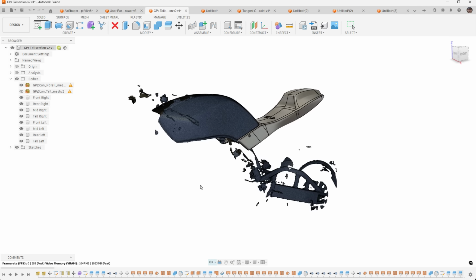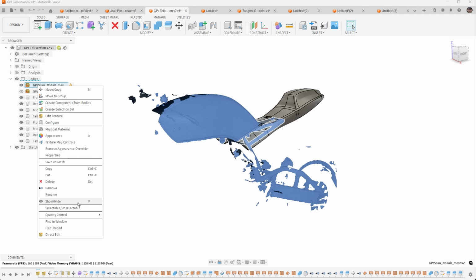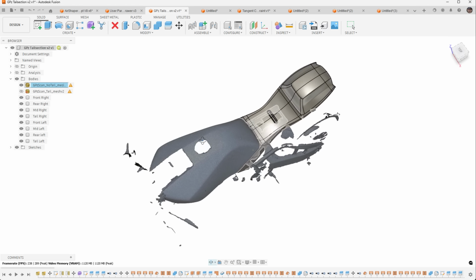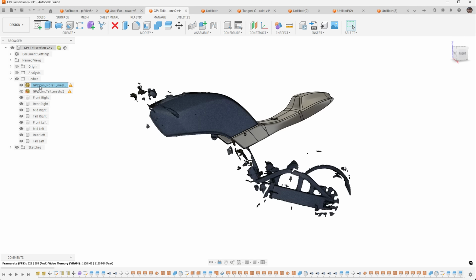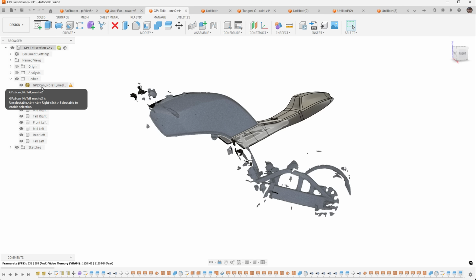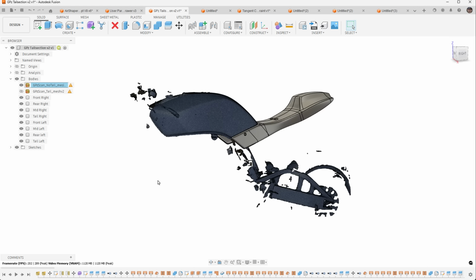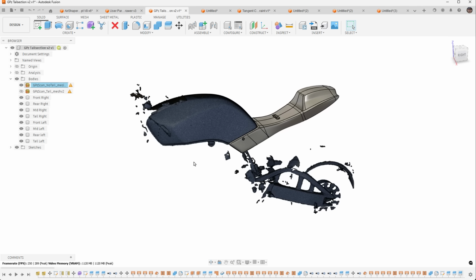And so if you're having performance issues or if you notice a lag, so right now we've got a large mesh here, and if I make the mesh selectable, one thing that we're going to notice is the performance typically gets worse because every time we hover the cursor over that, it needs to select all of the polygons. And so you can kind of play around with it, turning it on and getting an idea of how your system is performing.